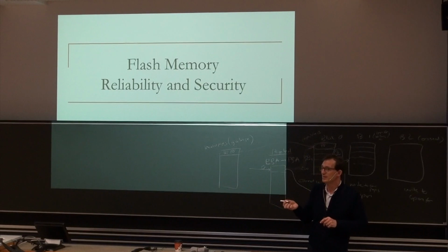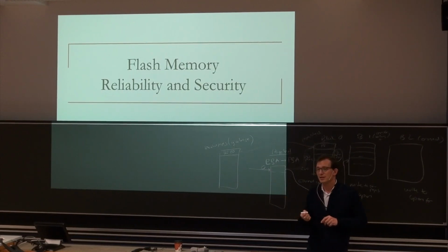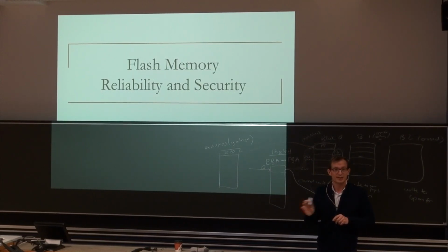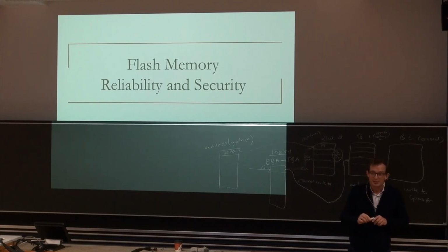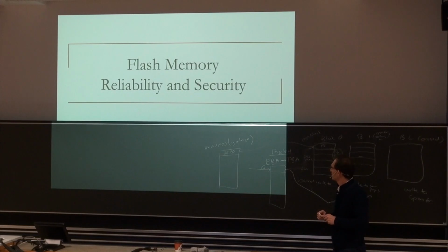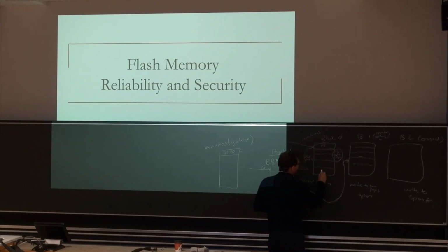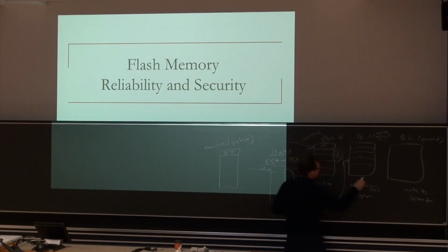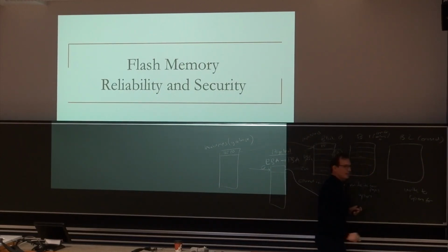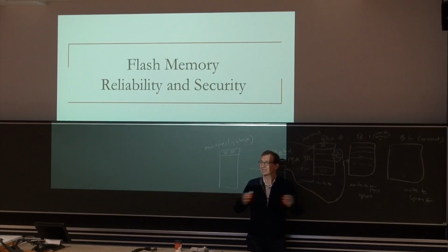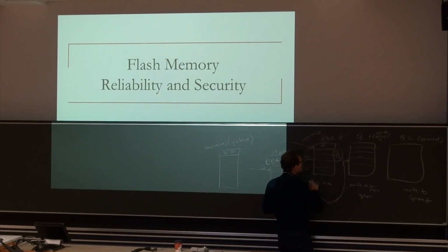A block, for example, you can only do 3,000 writes to a given block. 3,000 program and erases, or page. Now, if some of the pages have 3,000 over here, and some of them have 0 over here, that may not be good, right? Because you're not utilizing your entire drive. Some of them become unusable quickly.